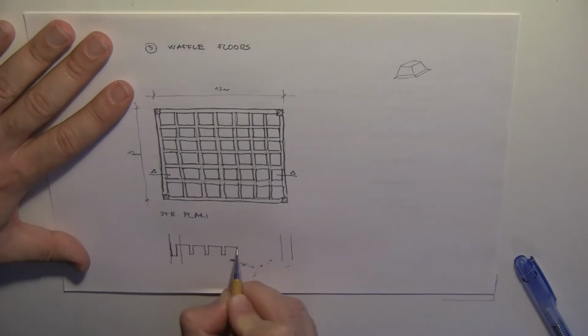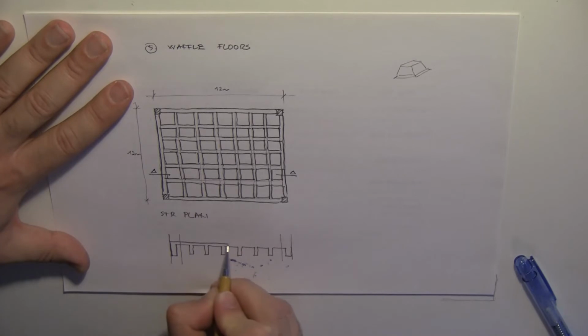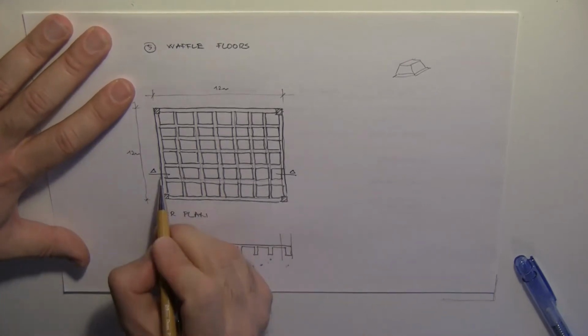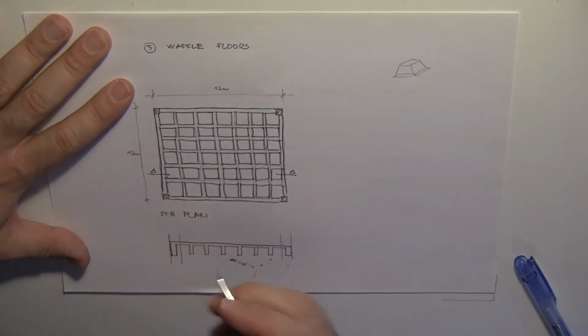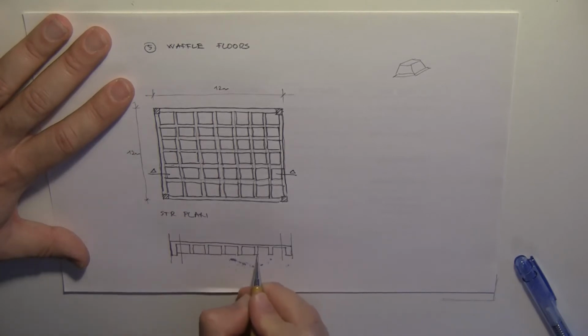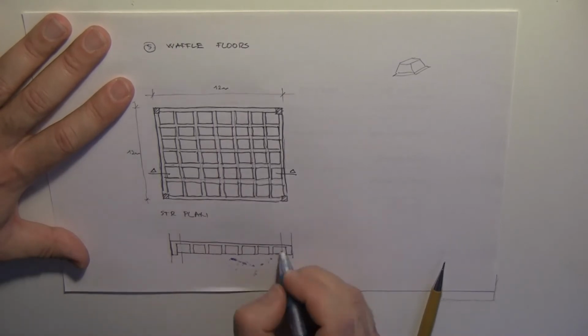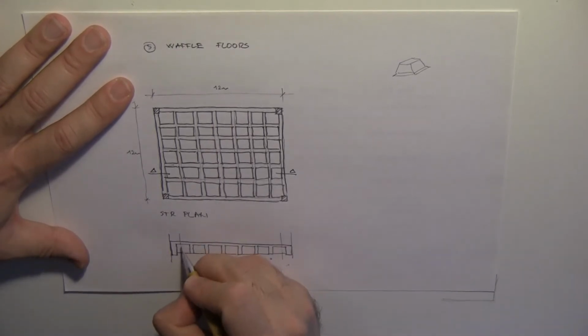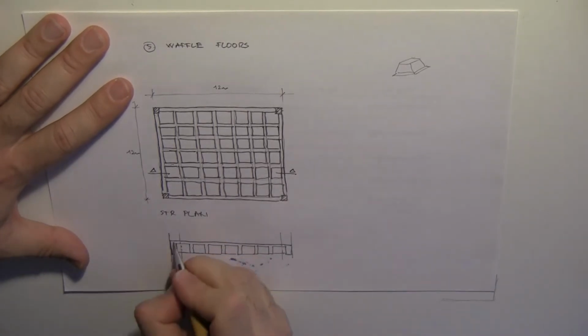I have got lots of beams, 1 by 1 or maybe 2 by 2 squares we are talking about. Now that this section is passing from here, that secondary beam on elevation is again going to hide the column. So I need to erase this line again and draw it with dotted lines. And let me hatch it.